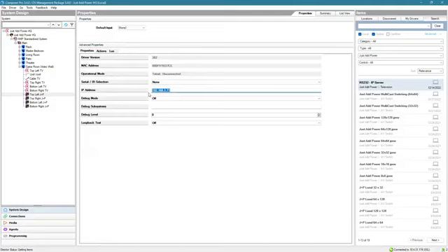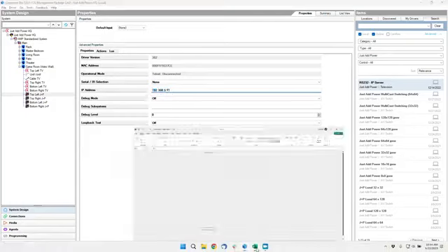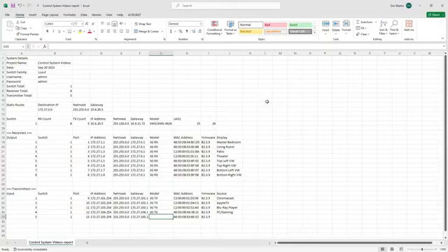We've already configured our system, so we just need to put the IP address of the receivers behind the TV. We're going to find that in our report file for our system as we built it. So we've got our master bedroom, living room, patio, theater. We've got all of those already programmed. Now we've got our top left, top right, bottom left, bottom right. So we're going to go over here to the IP address column. We're going to see the IP address of those 4 receivers in the wall. So we've got 5, 6, 7, and 8.